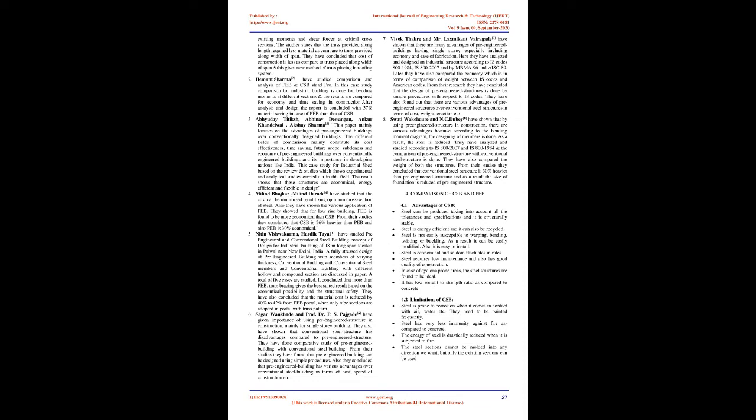It concluded that, more than PEB, truss bracing gives the best suited result based on economical possibility and structural safety. They have also concluded that the material cost is reduced by 40% to 42% from the PEB portal, when only tube sections are adopted in the portal with truss pattern.